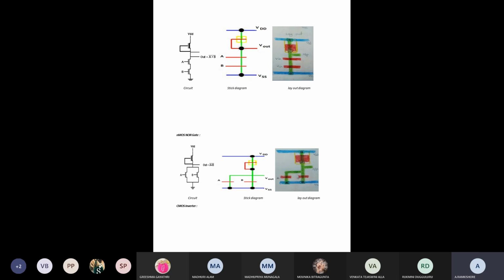So here we now have to see a two-input NAND gate. So the expression for the NAND gate is y is equal to a dot b whole bar, a dot b whole bar. So here we have the dot, that means AND operation, multiplication operation of one variable with another variable. So in case of the NMOS, we have to connect those two variables in series manner.